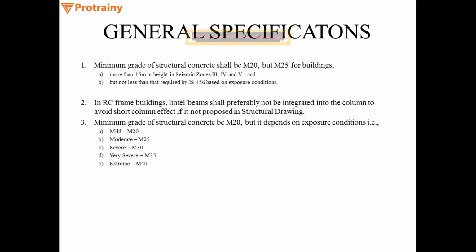Where M20 or M25, the last numeric value shows its characteristic strength, and M stands for the mix. Coming to another point, in RC frame buildings, lintel beam shall preferably not be integrated into the column, because of the short column effect, if it is not proposed in the structure drawing. So if you get a structure drawing on site, and it is not mentioned in the structure drawing that the lintel should be integrated into the column,